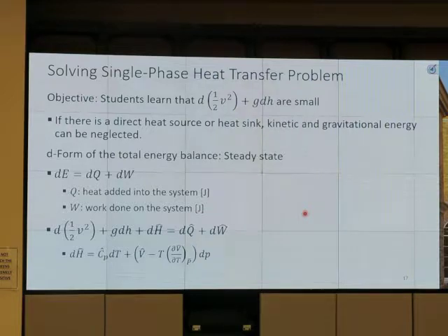The case where heat transfer is a concern for multi-phase flow and single-phase flow is the subsea pipeline. We may just say, hey, insulate the pipe. How much? How do we insulate the pipe? How thick is the insulation layer thickness? If we put too much, it's expensive. If we don't put enough, we don't have insulation. So we have to do a calculation for the heat loss. So this is for the case of a subsea pipeline.